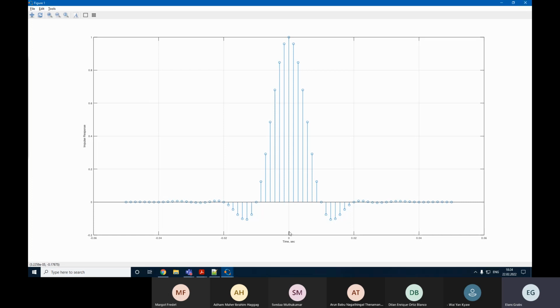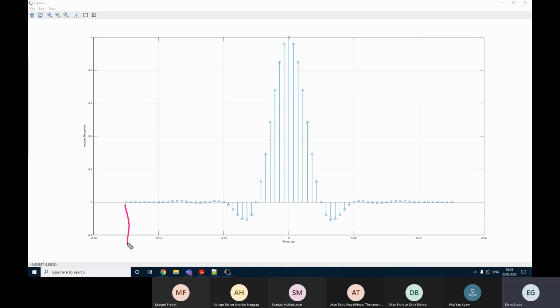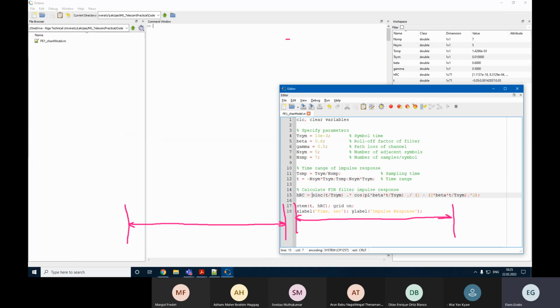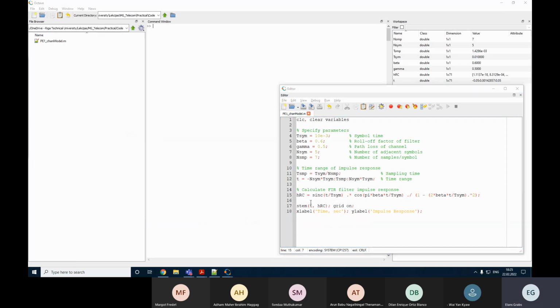Here we have a 0 time interval, and our delay is going to be from here to up to here, right? So basically, this number of samples is going to be our delay, which is exactly half of the impulse response except for this central node. Now, however, considering that we have complete symmetry here, this is going to be odd number anyway. So if we divide this total length of the impulse response with 2 and take the lower part, yes, then we are going to find our delay. So let us find this delay, right?